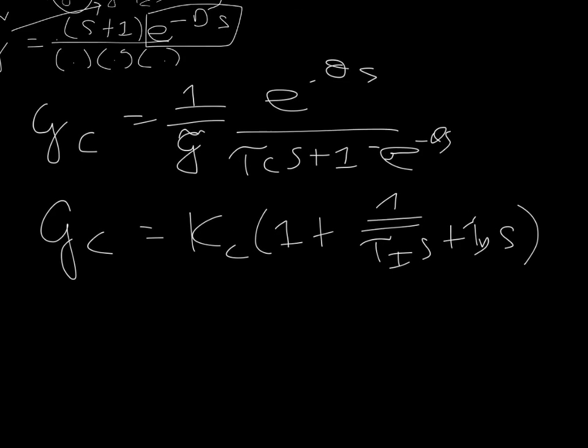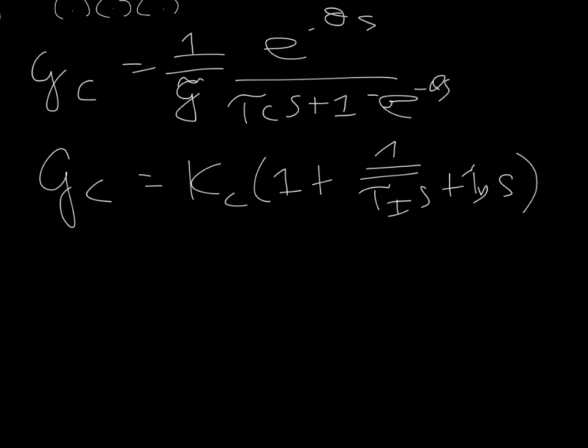So one of the ways in which we'll use the direct synthesis technique is, the straightforward way is to calculate this and then simulate GC or build a controller that is exactly like this. A more practical way is to say, I have one of these, now I just need to figure out the parameters which will match GC, this PID controller, closely to this relationship over here.